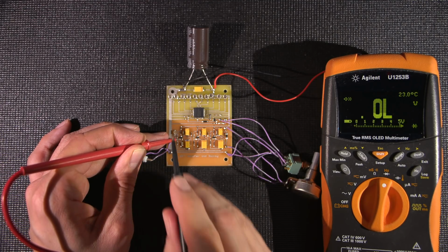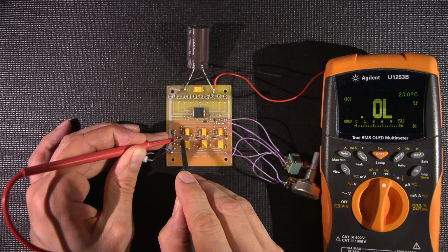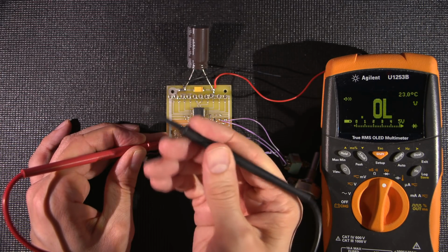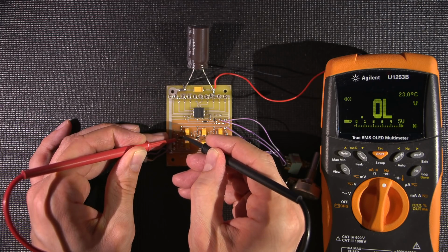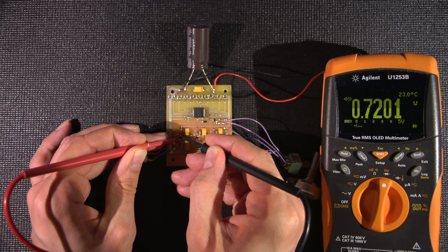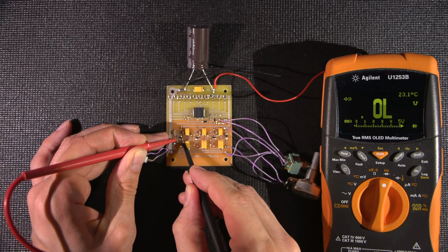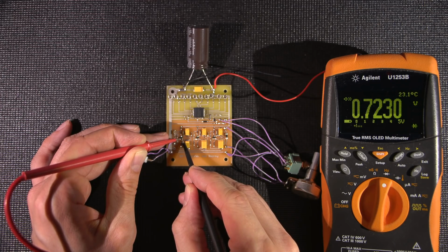All right, so now I'm going to check the pin at the top side and watch what we see on the meter here, right? So I'm going to touch the negative lead of my diode checker to the collector here, right? You can see a diode. It's looking good. Now I'll move this down to the emitter, and as you can see, it's another diode. We just verified that this was an NPN transistor.